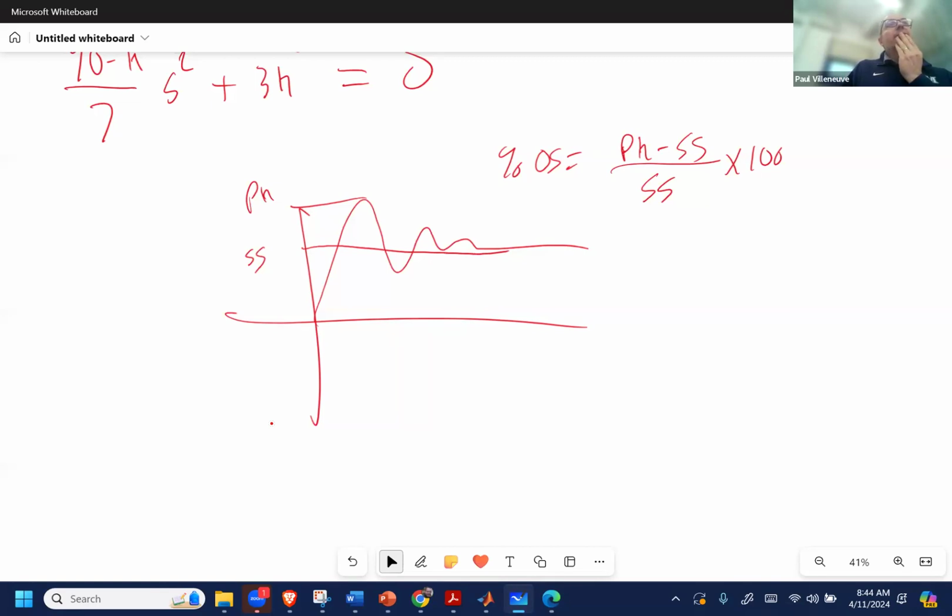Can you also see the error? Yes. So this is the steady state, but my set point is down here. What would be the actual error? The error is between here and here. Anytime after 5 tau would be what your steady state error would be. But I would just use the steady state error tables to calculate it, though you can read it off a plot. This is your set point, and this is what you've got, and the difference between the two is the error.